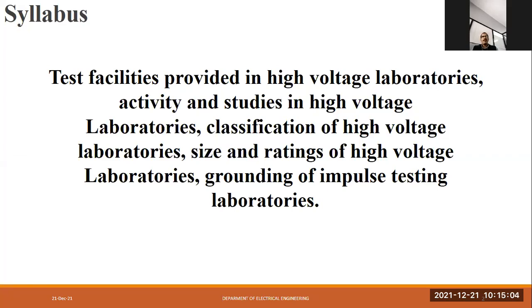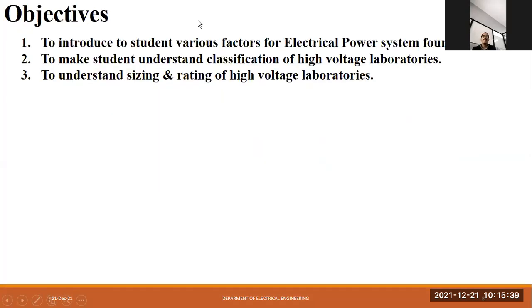That is very important, as I discussed earlier in the last lecture, every high voltage rated electrical equipment should be grounded properly, right? Due to that grounding, whatever the damages, or the surge current due to lightning strokes as well as surge strikes, that induced impulse current, which is the highest current for a particular moment, will go to the ground, where it gets a low impedance path.